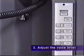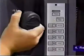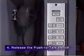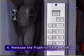Adjust your voice level so that the far right LED on the page level meter only flickers occasionally. Release the push-to-talk switch when finished making the announcement. The system will turn off the page and return to its pre-page condition after a short delay.